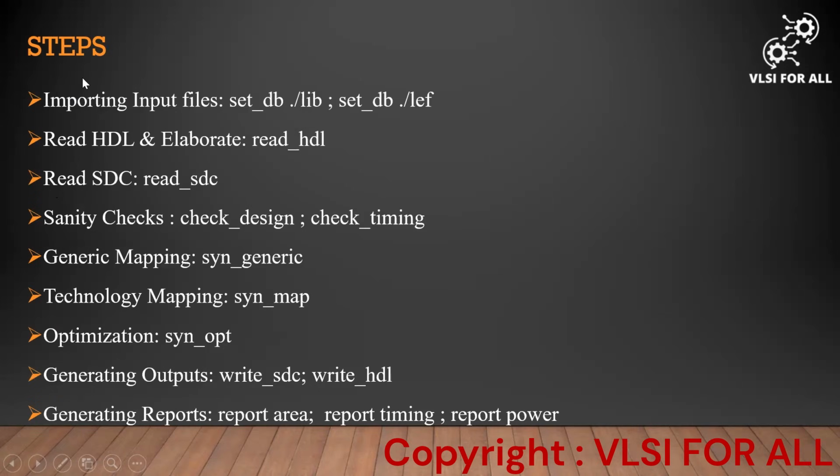Next, coming to the steps. What are the steps it performs in physical aware synthesis? In the first step, it imports the input files. Whatever inputs we have discussed earlier should be imported using commands. We can import all the input files, set_db .lib or .lef, likewise. The next step is to read the HDL and elaborate, which means it will read all the files we have provided and perform the elaborate stage, as we discussed earlier in the logic synthesis flow. For this, the command is read_hdl. And the next step is read SDC, which means the command is read_sdc.